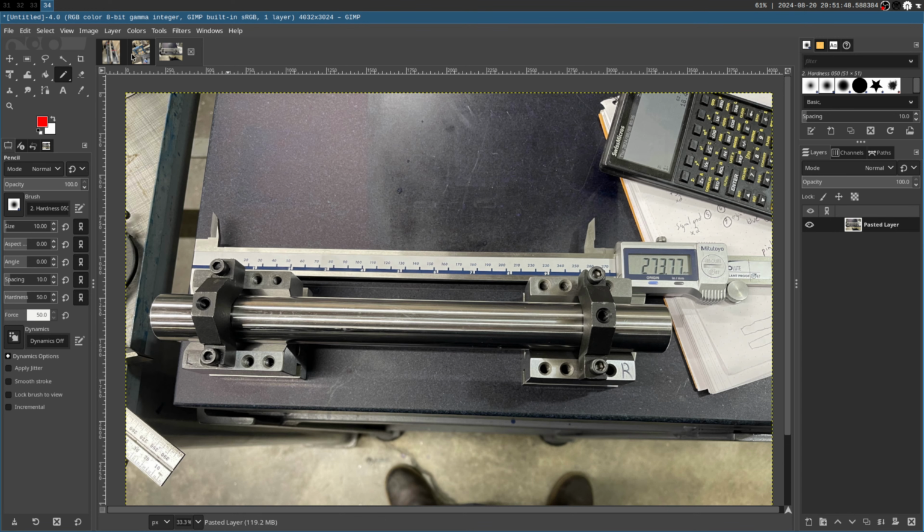So, yeah. Wolf the Great asks, would you calculate the stresses and how much the bed would bend under the load of the spindle and rear headstocks and apron in SolidWorks to compensate for it during scraping? No. What you do is, basically I get everything flat and parallel, and then I'll set the headstock in. I'll measure how the headstock is running with respect to the bed, and then I'll take the headstock off, and I'll scrape underneath the headstock, right?